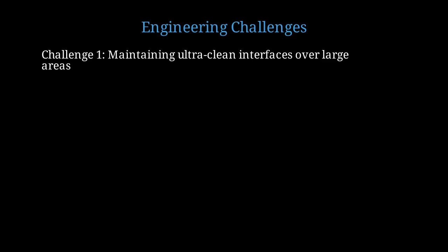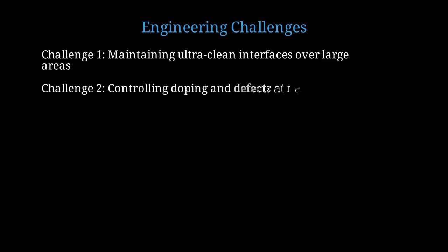Engineering ballistic transport in practical devices presents several major challenges. Challenge 1 is maintaining ultra-clean interfaces over large areas. It's difficult to fabricate devices with atomically smooth interfaces over technologically relevant dimensions. Challenge 2 is controlling doping and defects at the nanoscale. Even a few impurity atoms can significantly affect transport in a nanoscale device.